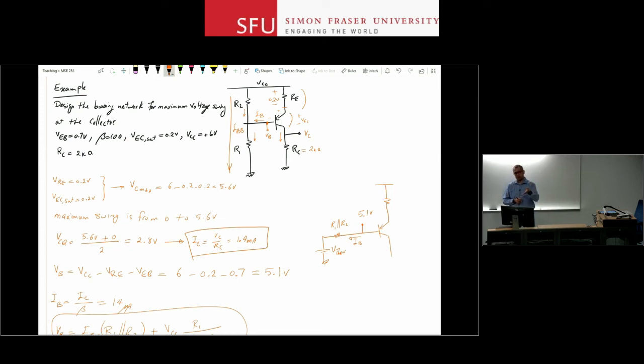Now you can do the simulation, right? So you have R1 and R2 values, and then you have to move slightly above that region, up or down, in order to get the values that you want for the current. So let's say you want to choose E12 values, you just go and play around with what you chose initially. But that's the process, right?